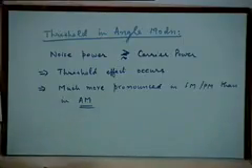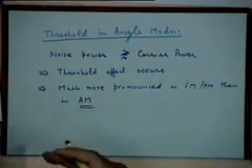Invariably, the threshold effect is a phenomenon arising from the nonlinearity in the system. As long as you are doing synchronous demodulation, your entire system, modulation and demodulation, was a linear system. The moment you put in an envelope detector, it became a nonlinear system. In the case of angular modulation, modulation itself is nonlinear, so the system is nonlinear, and therefore the threshold effect will occur.